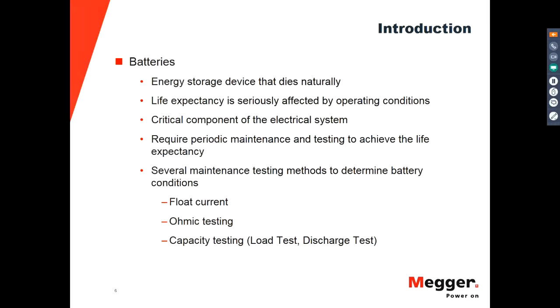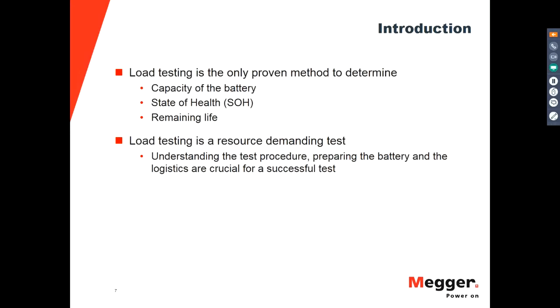And then you have the capacity testing, which is the one that we are talking about today. This capacity testing, also called load testing, is the only proven method to determine the actual value of the capacity of the battery. It's also the only way to determine what's the state of health of the battery, or the only way to see what is the remaining life in the battery.